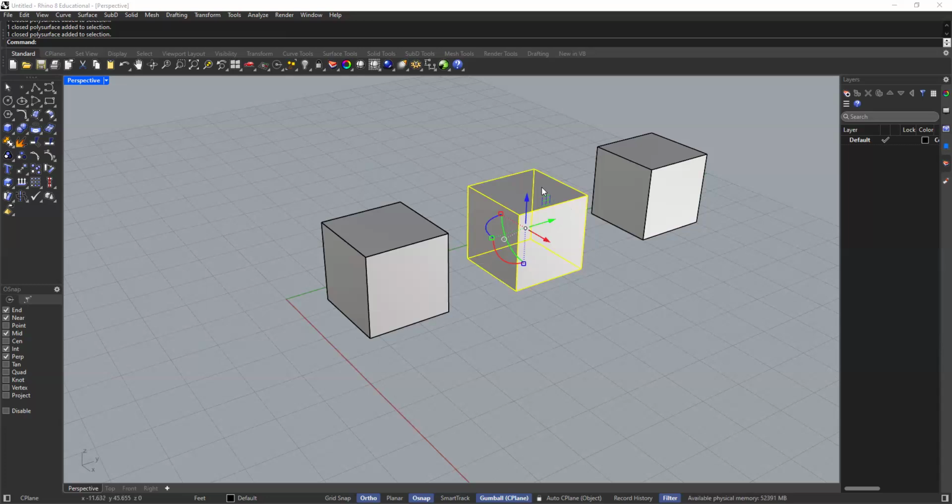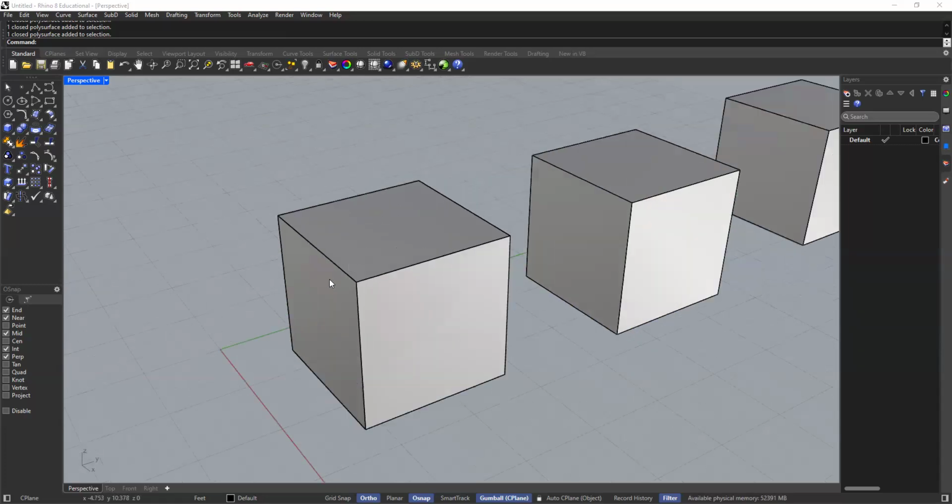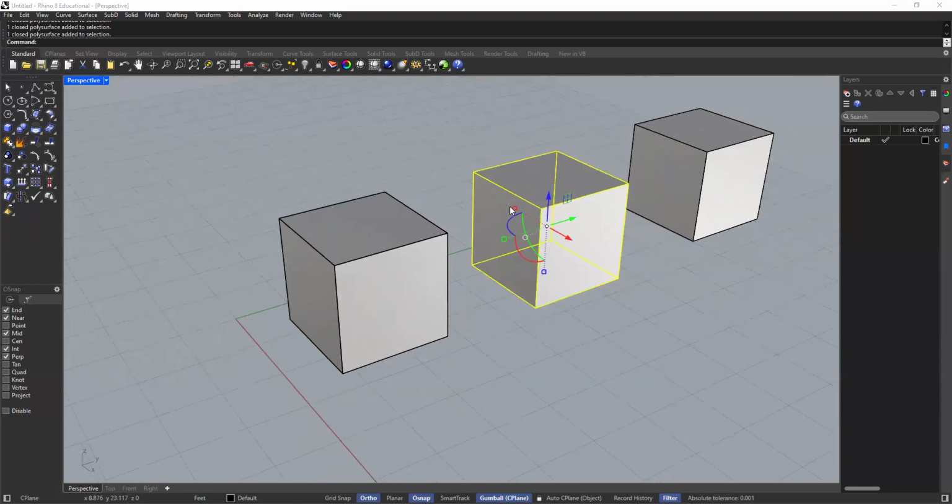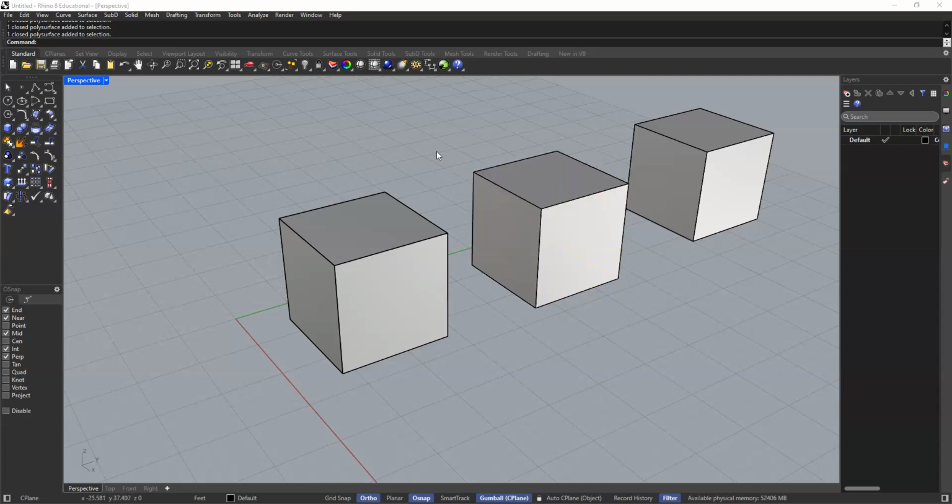Okay, so hopefully now we have an understanding of the difference. What is a polysurface? It's an actual object, it's a solid object. What's an extrusion and what's a surface, right? And when we model, we want everything to be modeled as a polysurface. And if you ever find yourself in a situation where it's close to a polysurface because all the walls are joined, but you're missing a top or a bottom, then you use the cap, C-A-P command.